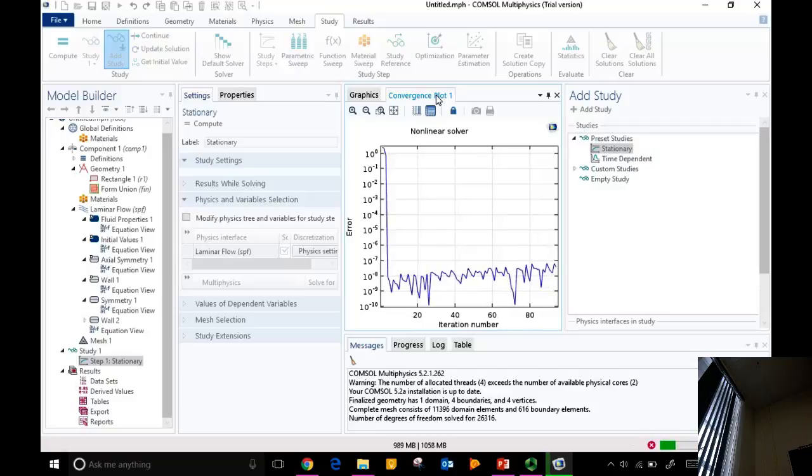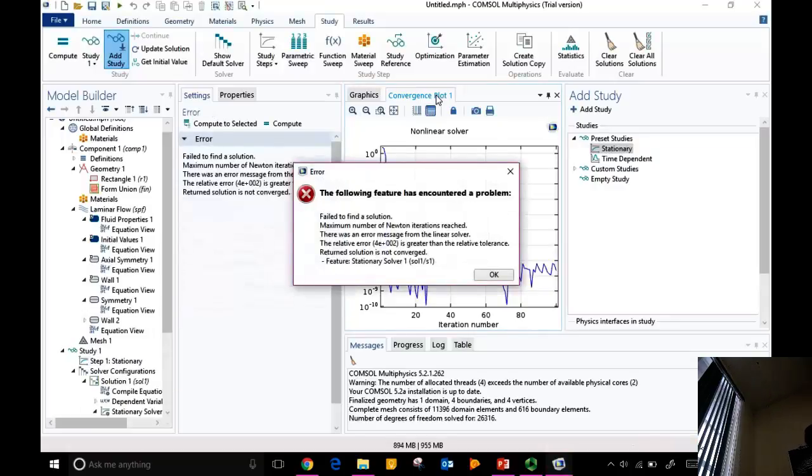So this is a tank with a free surface. Okay? So the shear stress on both sides is the same. But because this is air and this is water, you can say that the viscosity of one is close to 0 because one is 1,000 times smaller than that. Then you're saying that the gradient of the velocity is 0. Then it becomes the same as a symmetry boundary condition. But in the symmetry boundary condition, whatever happens below happens above. That's the implication. Whereas in a free surface boundary condition, the gradient is 0. And the impact of that on the equations would probably be the same.